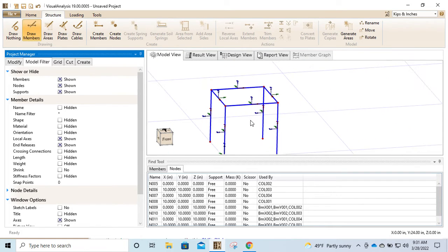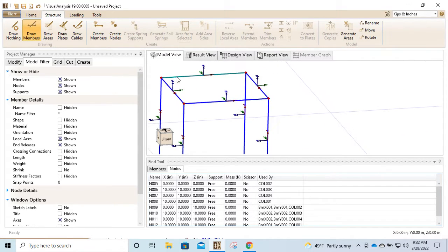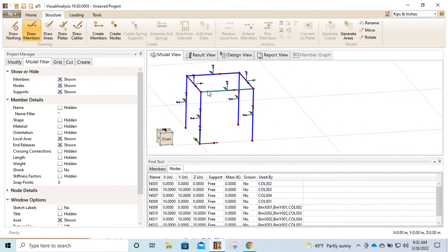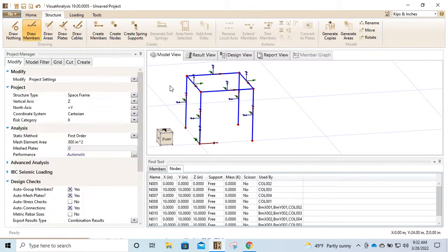So if I wanted to, say we just wanted to build a frame, right, just like this, and we were going to apply some loads on it, right? Say it was sitting outside, say it's the frame that's sitting over the HVAC system out here, right? 4 columns, flat on top. We would start by drawing our members, right? We have columns, we have beams that interconnect.